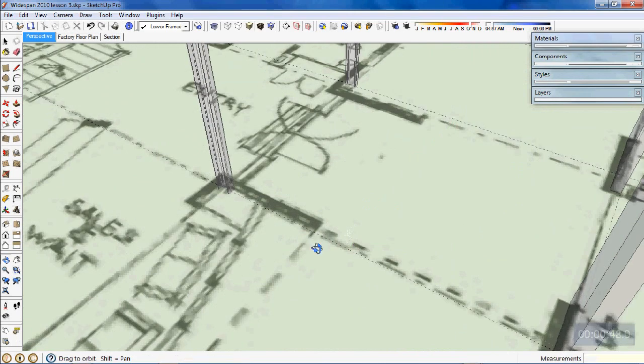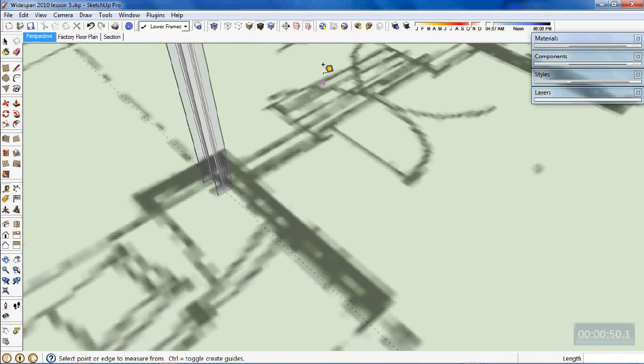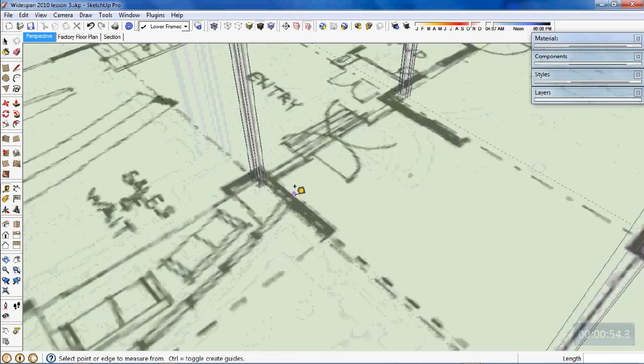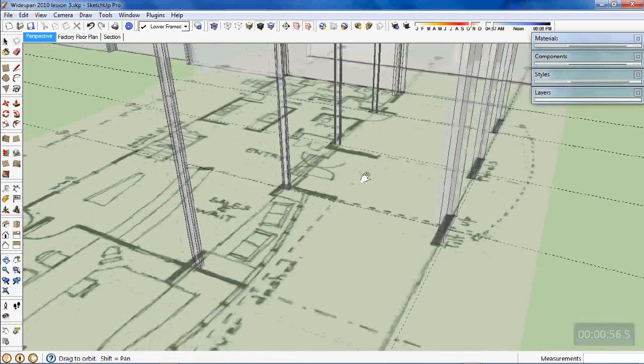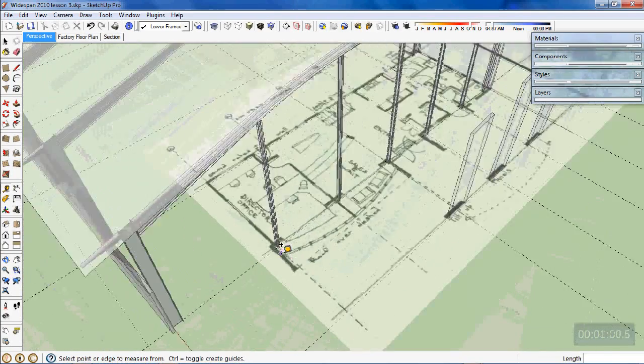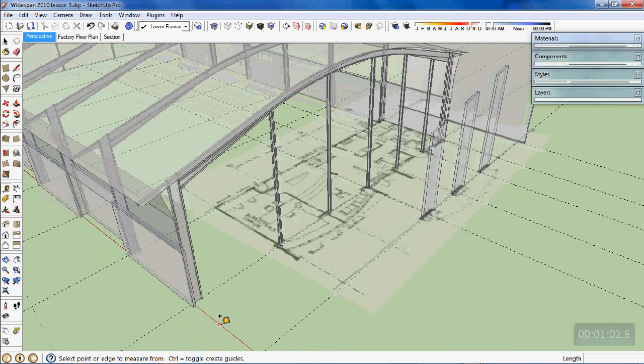If you've worked through this exercise in class, we've actually used some slightly different dimensions for this, so it won't matter. Whichever set of dimensions you lay out will just be a little bit different. Now to reinstate this last grid line here, I'll come back remembering the overall width across the overall grid lines was 24,900. Remembering this one was divided by 4 at the back, and it's in line with the one at the back, so it's 24,900 divided by 4 to that one.